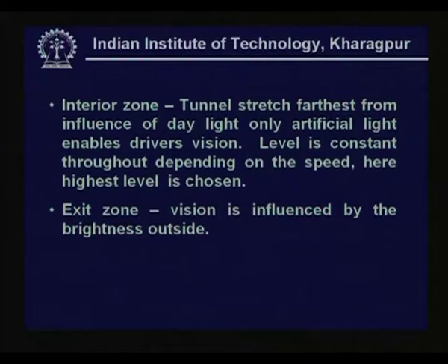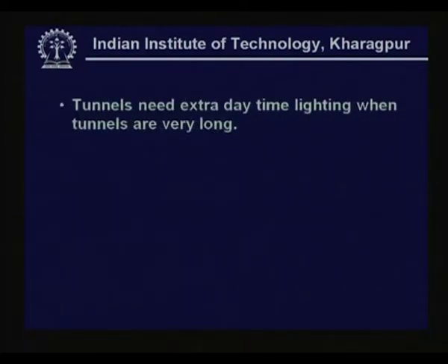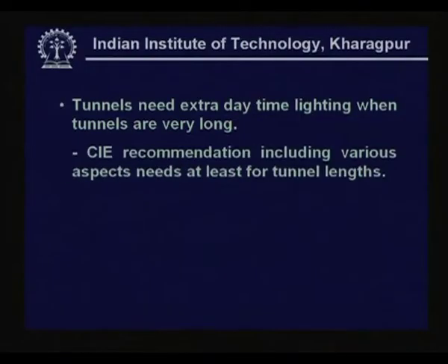Again, this is the zone where the influence of the brightness from outside begins to appear because he is about to come out. So, these are the 4 zones which are there in tunnels, and it must be mentioned that in view of bright light during the daytime outside, tunnels need extra daytime lighting, more so when the tunnel stretch is very long.